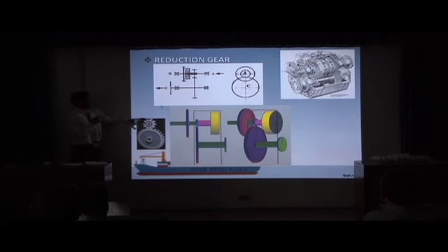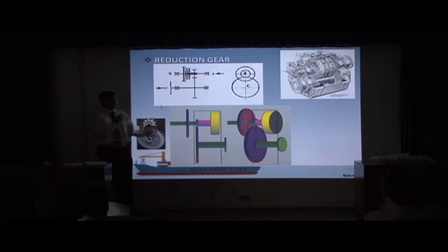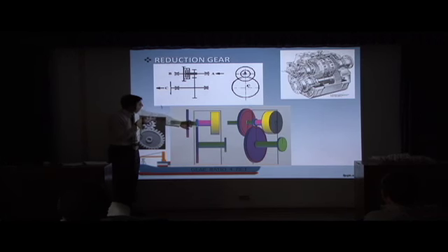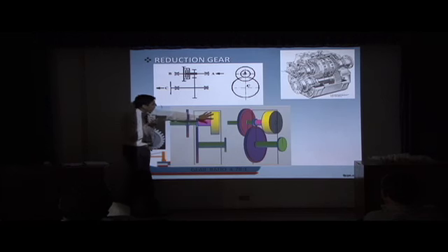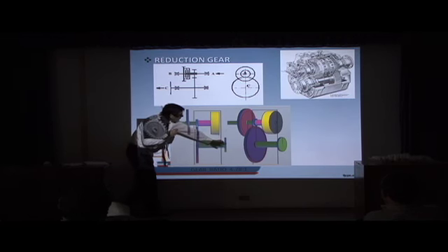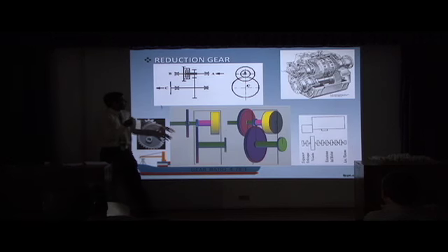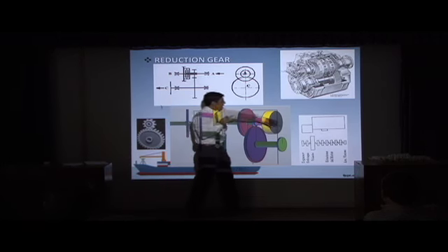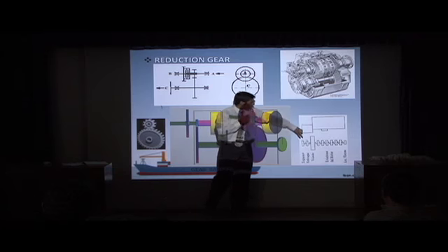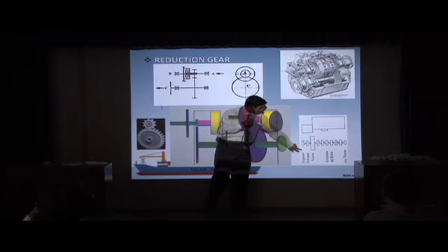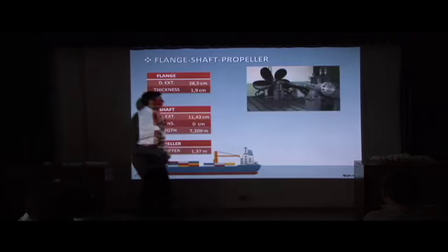Well, this is a system, but we need to transform it into only this. For example, this is the flywheel. This is the pinion, the gear, the clutch, and the flange. We use the gear ratio, which is 4.188. How do we next calculate this inertia? We have two new discs, in the gear and the clutch.